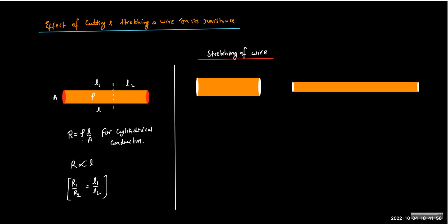So there are many objects which upon stretching increase the volume. There are many which decrease the volume. But in case of metal, we are going to assume that the volume is an entity which remains constant. Okay? So the simple rule that we are going to follow is that in the stretching process, volume remains constant.